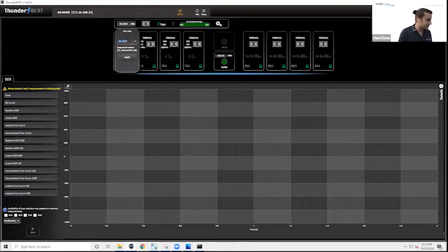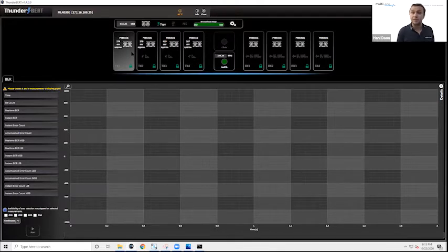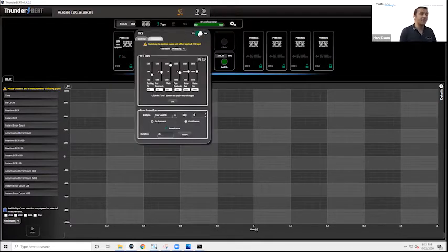Now, just as fast as 1 second, I can type in my bit error rate, and I immediately have a link on the RX side. We'll show you some of the ways that you can configure your transmit and receive side. As you can see, I have an on icon that I can toggle off for any transmitter. You'll see I turned off my TX1, and because TX1 is connected to RX1 in loopback, I lost lock right over here. I'll switch it back on, and I'll get my lock back almost instantly.